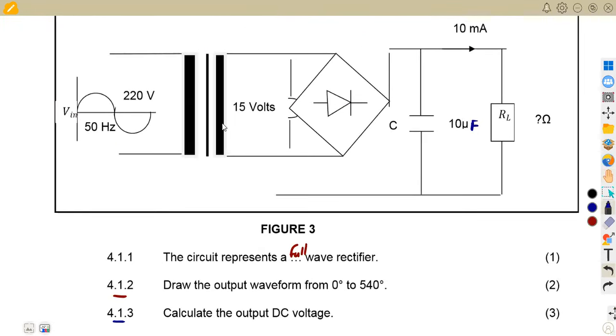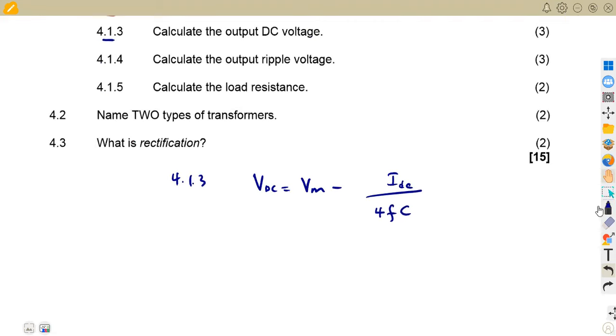All right, so considering our VM, this is the voltage that is entering, which is the one at the rectifier, of 15 volts in this case. We're going to take this VD, which is actually our VDC, that is the maximum value that we can obtain, of 15 volts, from the AC that we are having at the input. This is the input to the rectifier, but it's an output from a step down that happened from this transformer. So we are going to consider this as our VM.